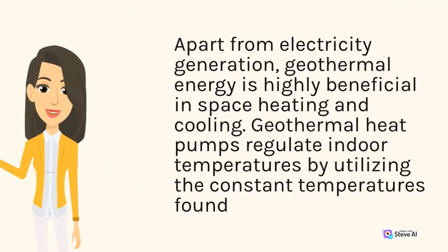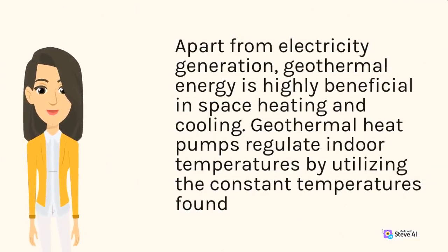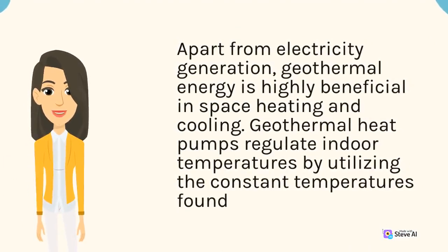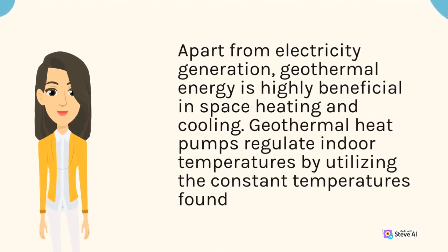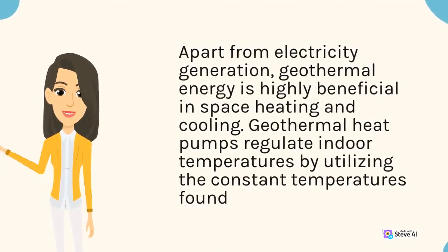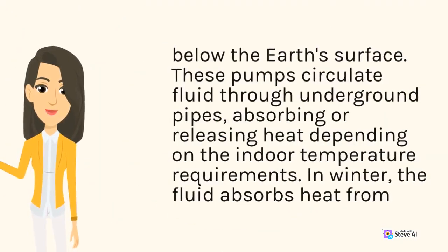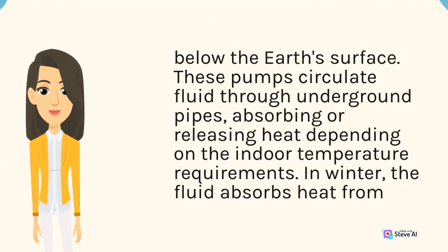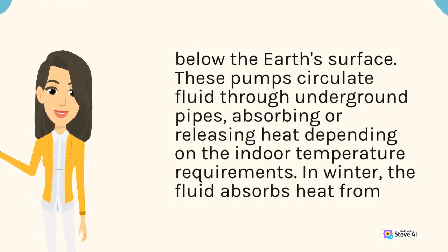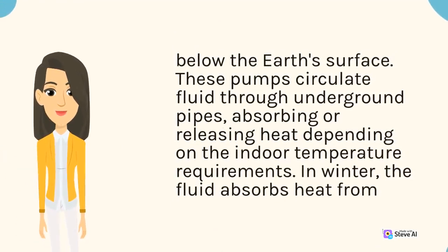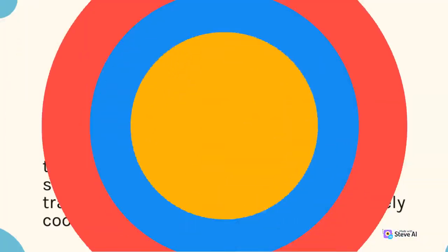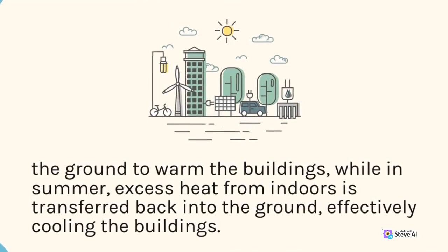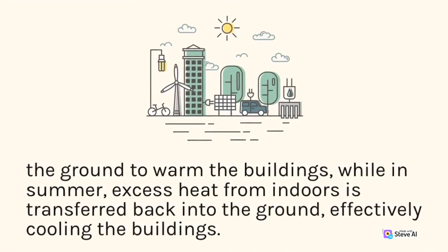Apart from electricity generation, geothermal energy is highly beneficial in space heating and cooling. Geothermal heat pumps regulate indoor temperatures by utilizing the constant temperatures found below the Earth's surface. These pumps circulate fluid through underground pipes, absorbing or releasing heat depending on the indoor temperature requirements. In winter, the fluid absorbs heat from the ground to warm the buildings, while in summer, excess heat from indoors is transferred back into the ground, effectively cooling the buildings.